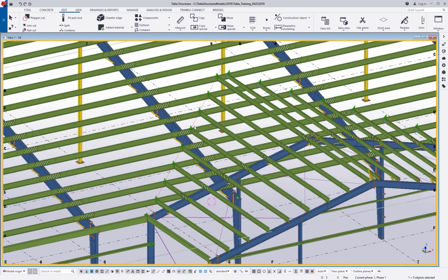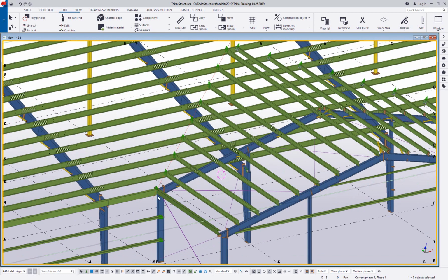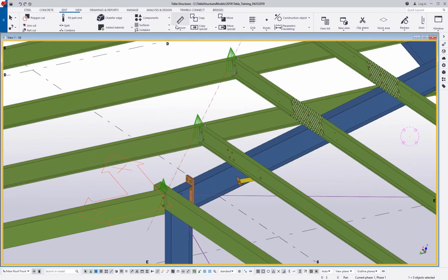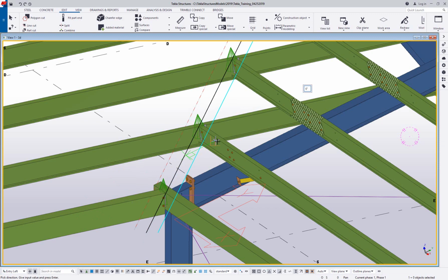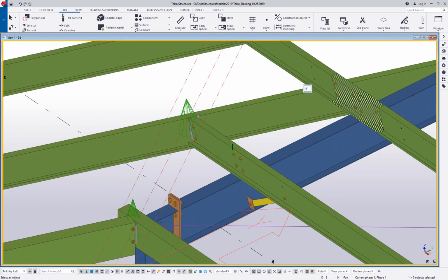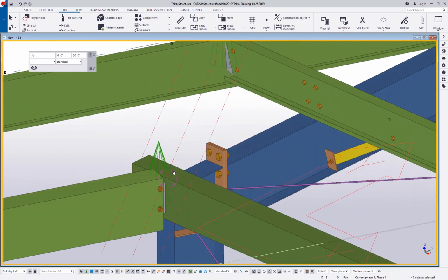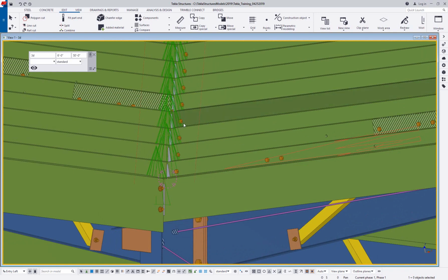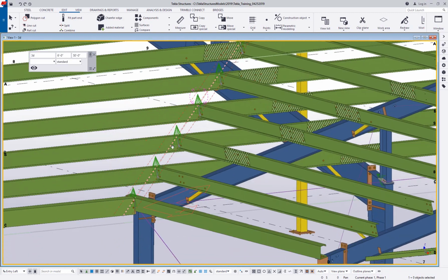And now I can offset this 6 inches in each direction, but I'm going to do it based on those work planes. So first I'm going to do it for the main roof front. We'll go ahead and use the copy with offset option here, and I want this to be offset 6 inches. So we'll click on that and then hover along this top flange, and then I'll change this to the entry left, pick on this again, and then hover over an edge for where we want to copy this in that particular direction. So if I look closely at this, and I'm going to try to rotate this so we can see easier, we're kind of creating the offset up each side of that valley. So I hope that becomes a little bit more clear of what I'm trying to lay out here.